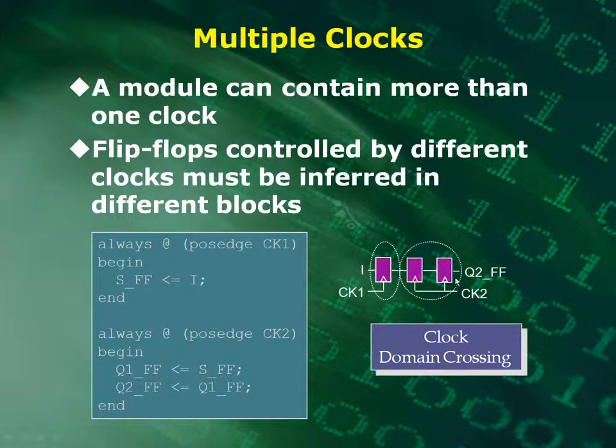Now, if you're taking data from one clock domain into a different clock domain, you can't do it directly. There are different methods you can use. This is one method. Let's assume that this clock here is running at, say, 10 megahertz, and this one over here is running at 20 megahertz. It's faster. Then this would be an acceptable method so that we don't have metastability issues.